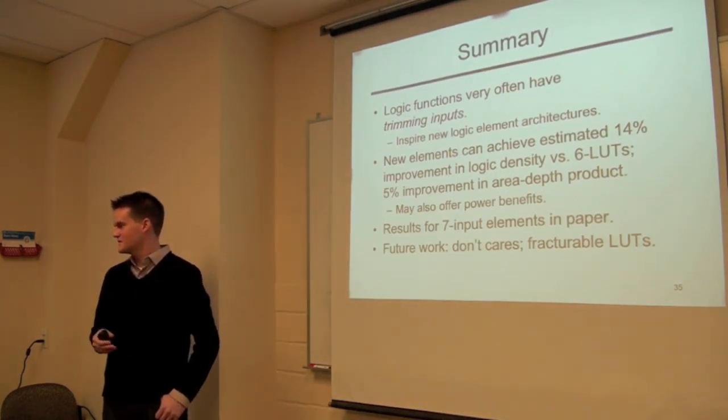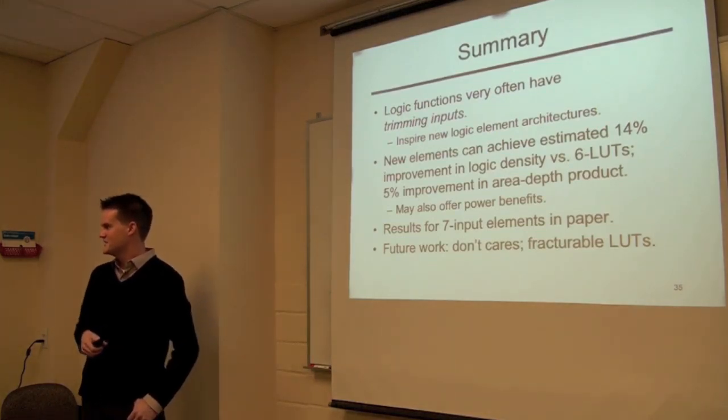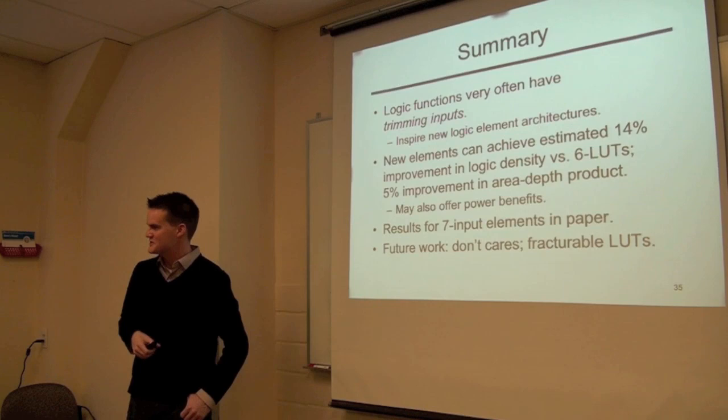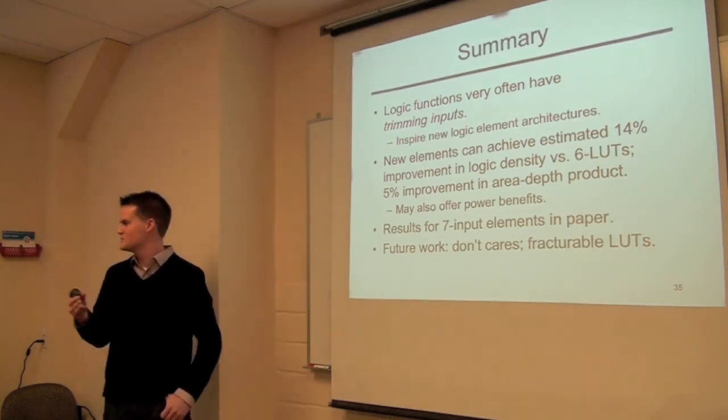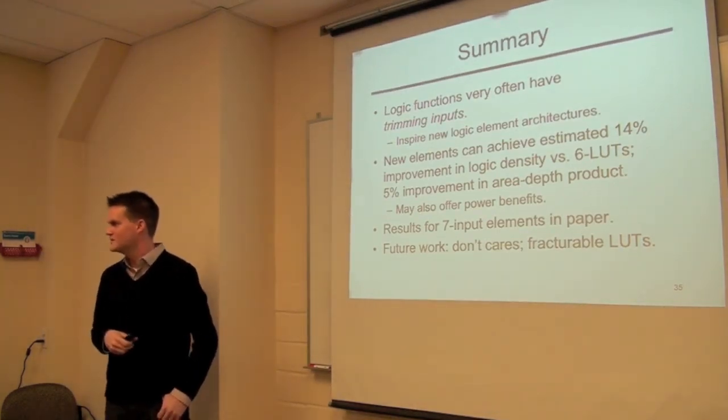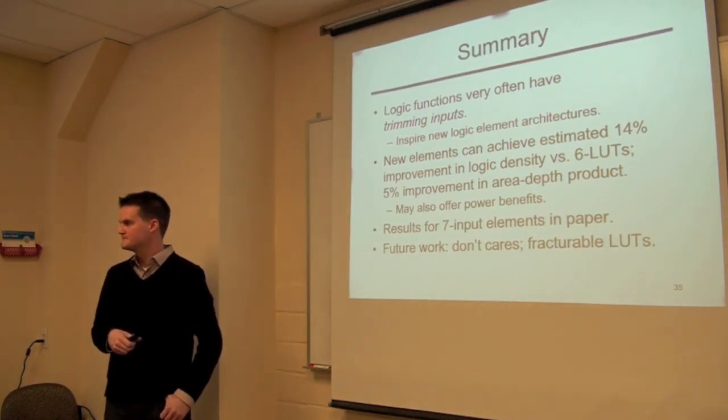Say you had a 6-LUT with two 5-LUTs inside versus now you have a 5-LUT and a 4-LUT; you kind of reduce the amount of unused circuitry. So yeah, I'd be with you, I guess you probably have less gain from fracturable LUTs. The gains might add up to more than just fracturable LUTs alone, though I don't know. Yeah, I think it's interesting, because I think there will be an interplay there.